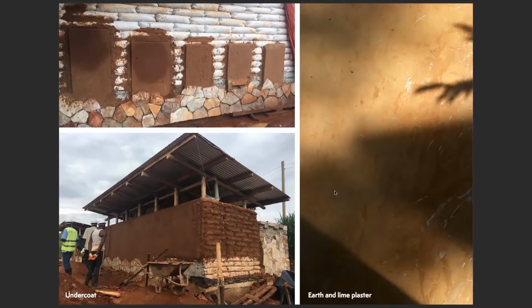More importantly, we need to make sure that the moisture trapped in this material manages to get out, and the kind of finishing that you choose needs to allow for that. What we are doing here is a series of coats of earth plaster, plain earth plaster with some sand. And to achieve good strength against erosion, we are using lime plasters, lime and earth plasters.